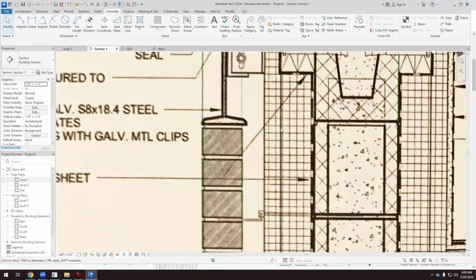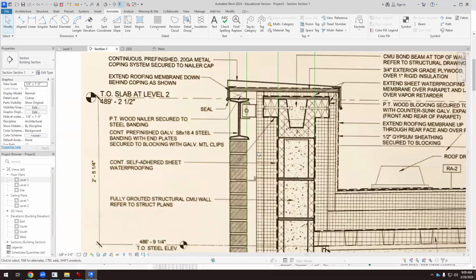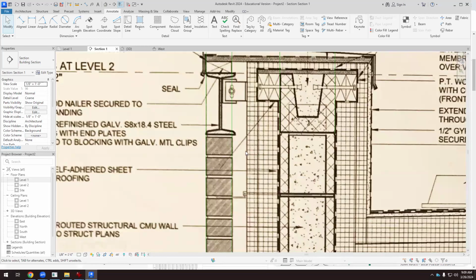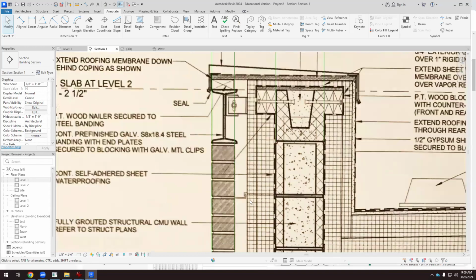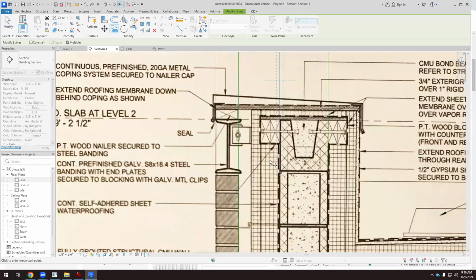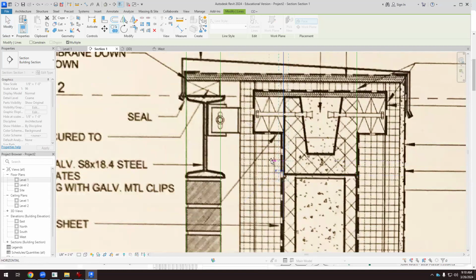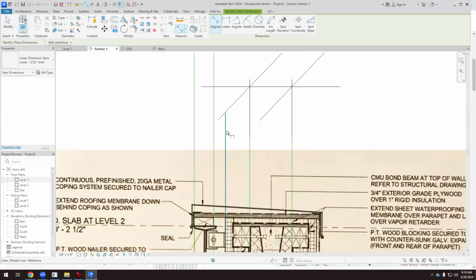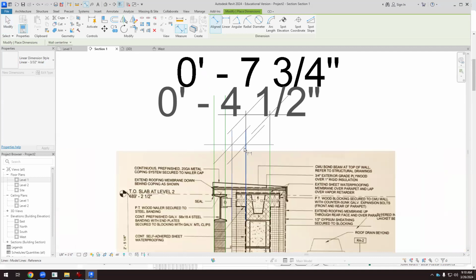Why is that? Because usually with thermal insulation, again, we can have 5 3/4 inches. We work with standardized panels. So probably we have a 4-inch and a 2-inch panel, so the width would be 6 inches. Can we find out if this width is around 6 inches? I can copy this line again, like here. And the distance of the thermal is, oh, it's 4.5.